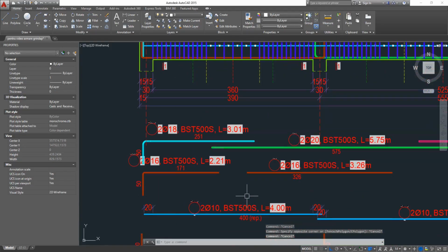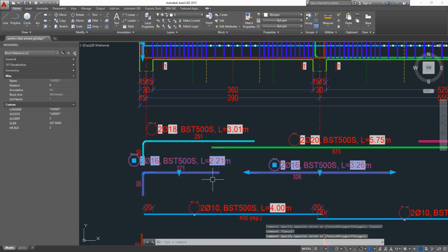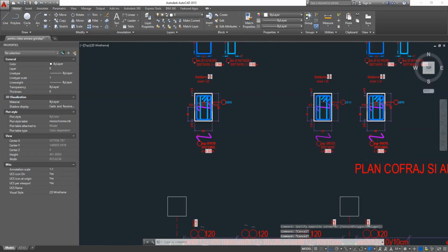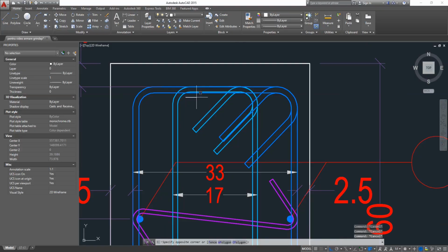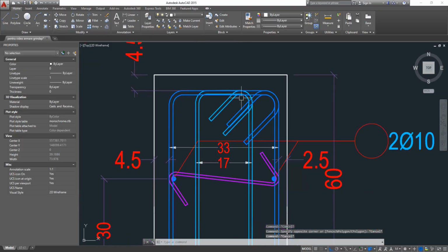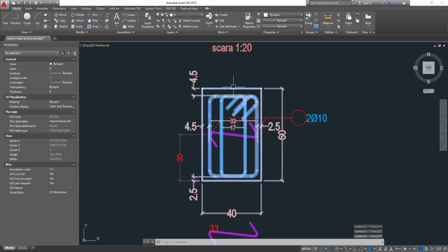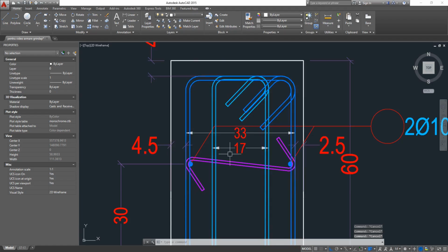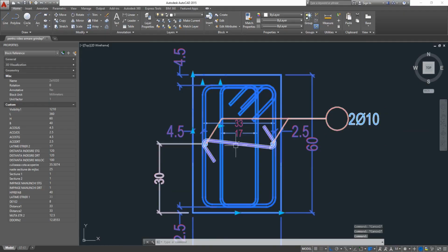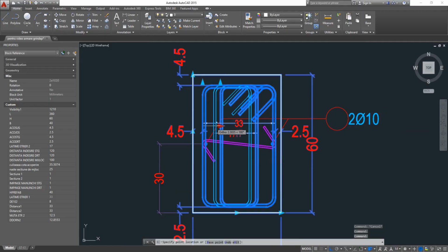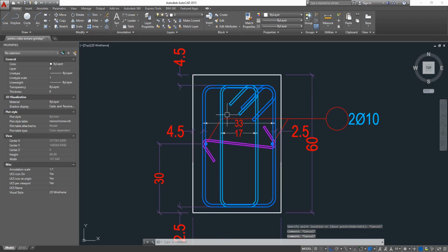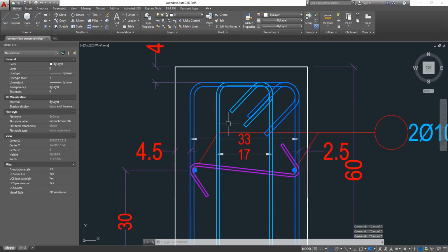And then for the second row of the top rebars, they will be placed with a second command inside the smaller stirrup. So remember, we gave different coverages to the carcasses. We made a specific width of the stirrup, and also, if we want, we can slide this one for each section as we want, according to the clashes of the incoming rebars.